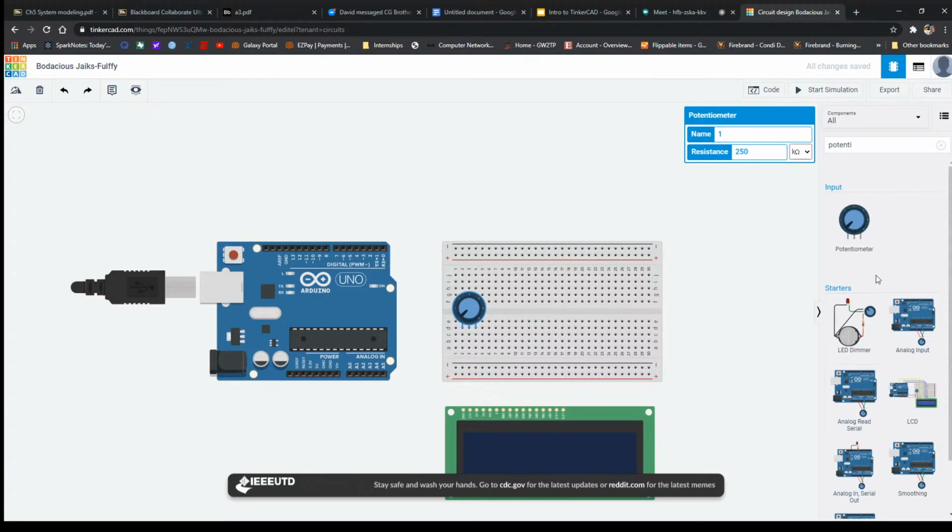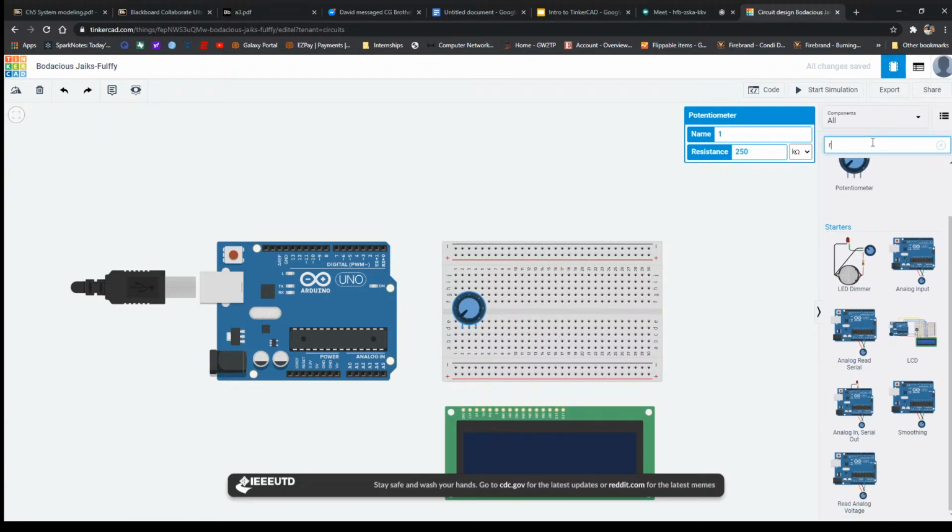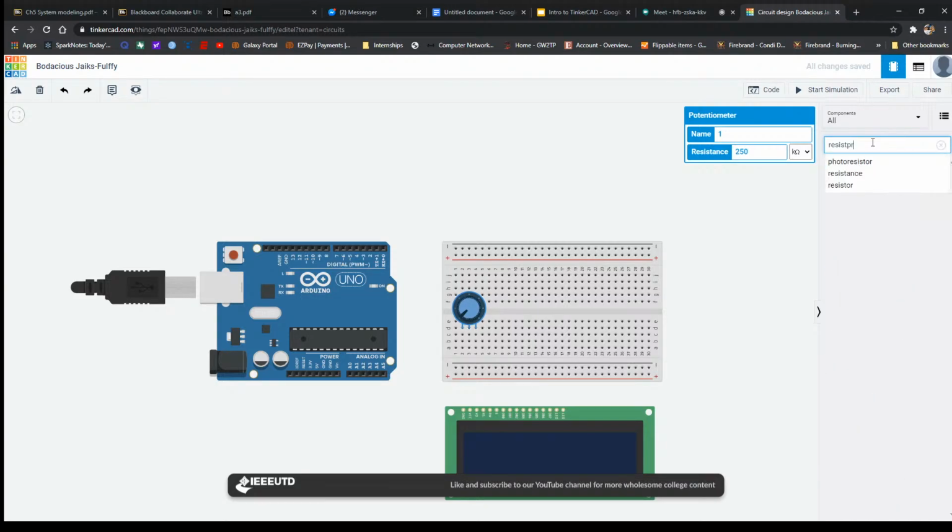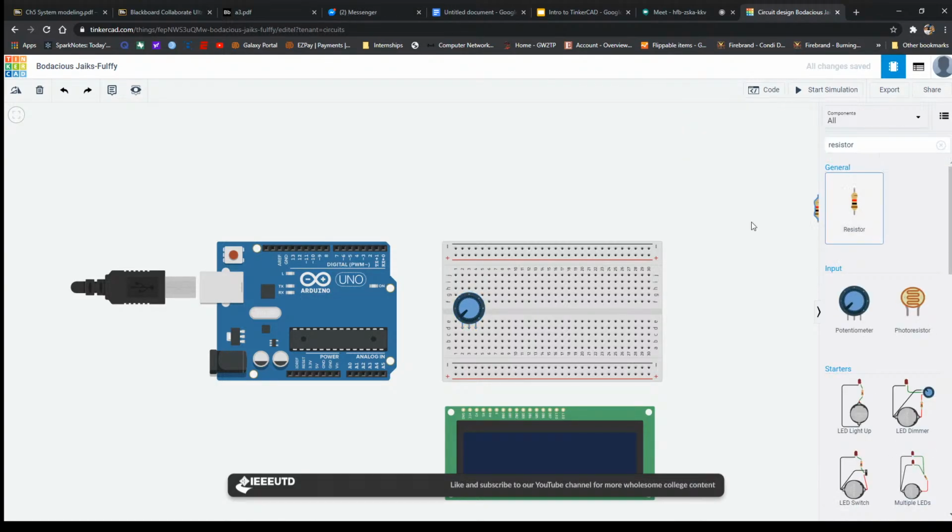And then last but not least, we're also adding a resistor. So we'll put the resistor right over here, so that one end of the resistor is connected to power, which will be connecting to the plus power bus here, and the other connection will be at the bottom, just right under it in this terminal strip.